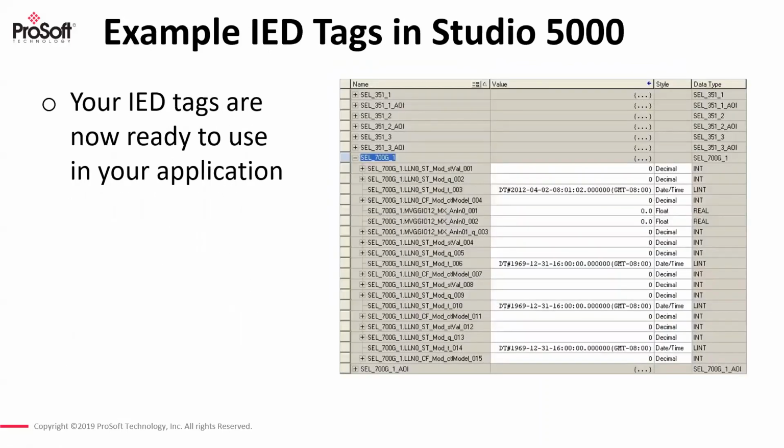Like I mentioned, that same tag name, LLN0.Mod.stVal, defined as part of the IEC 61850 protocol standard, is brought all the way through into the PLC code.